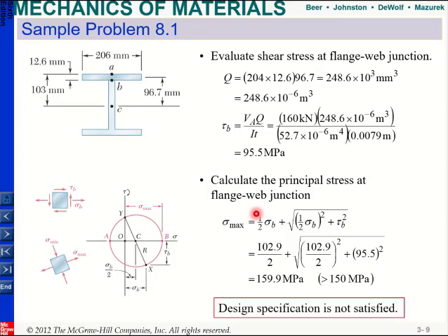All right. So this is just an example, and it shows that when we are looking at beams, especially if your cross section is not constant and the thickness is changing, there might be cases where you need to look at different points. For this beam, for example, A is critical because you have a maximum normal stress. C might also be critical because you will have the maximum shear stress there due to shear force.